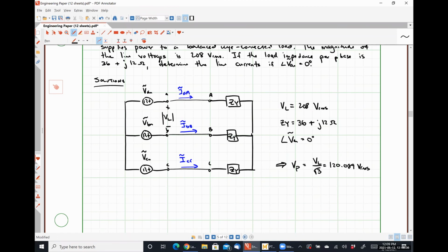So the delta connection, I think that would be 400. Let me do the math real quick. I just got to multiply 240 by square root of 3. No, not 240 squared. 240 square root of 3. 415.7. So that's the voltage for a delta connection at your house. But you would typically see it as 240Y.